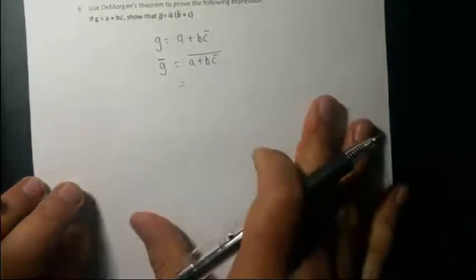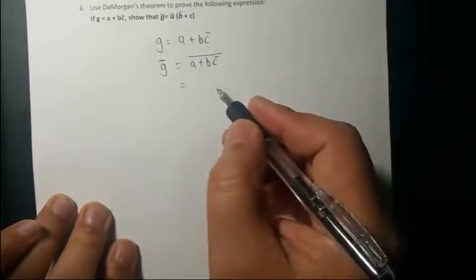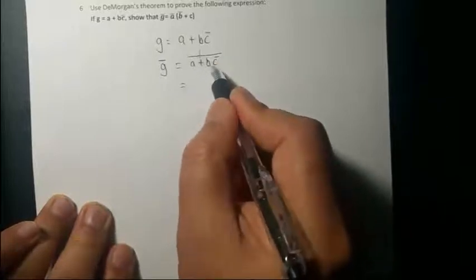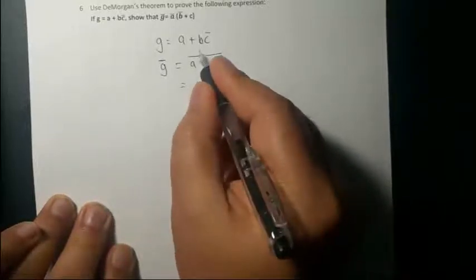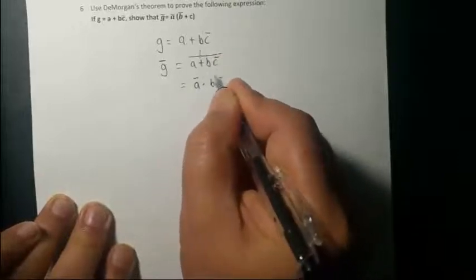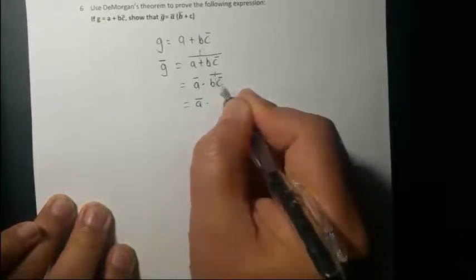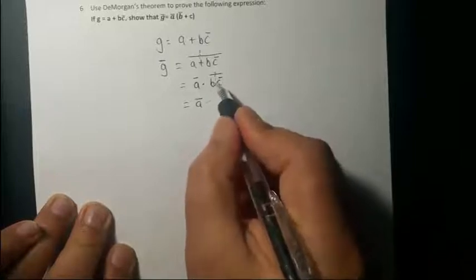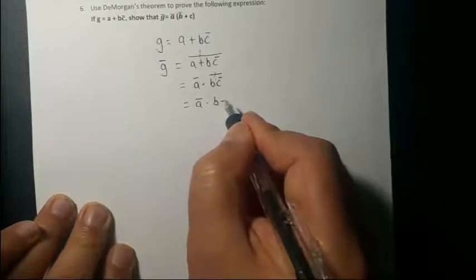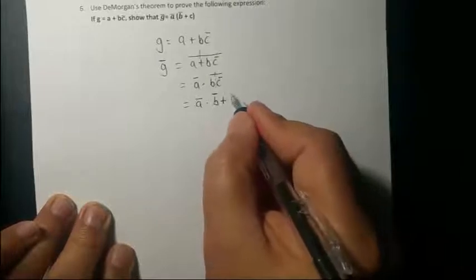Now, based on De Morgan's laws I showed you in the diagram, you can go back and check my lecture, you can break the long bar. The complement of the sum is the product of the complements. So if you break the bar here, it's going to be this product with B C bar. One more time, you break the bar here, and the complement of the product is the sum of the complements. So B prime plus, if you break the bar, C prime prime.